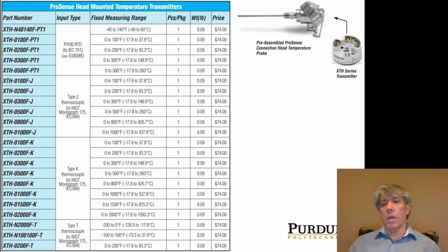Thermocouples are cheap. Thermocouples are where you take two dissimilar wires and you either twist them together or you touch them together and weld them together. And because of the dissimilarity in the metal, a small millivolt signal is generated that depends on the temperature at that junction. The higher the temperature, the more or less, I don't remember which, it changes the millivolt signal. And if you have appropriate hardware, you can determine what the temperature is based on the millivolt signal from that junction.